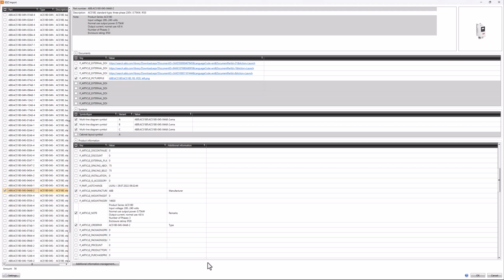You can also define your own additional informations, and all these values will be set for those additional informations. Why use the additional information? Of course, then you can use it in your list of devices and other things. You can actually do a bill of materials using our report tool from Electrical, and that way we will have the information working again.